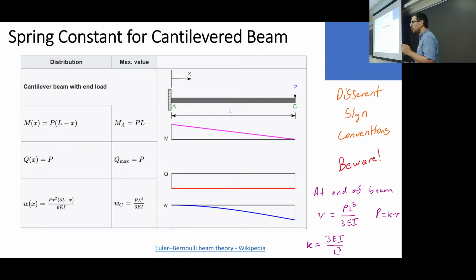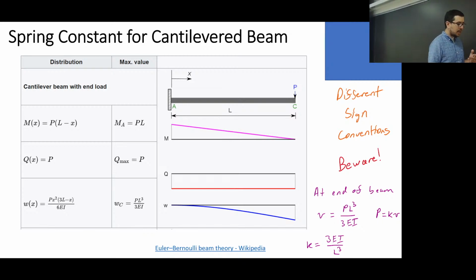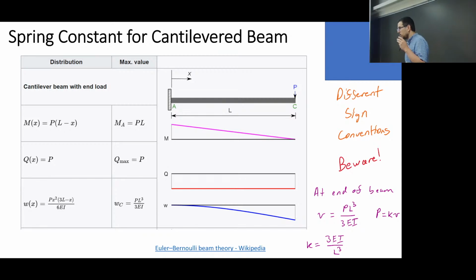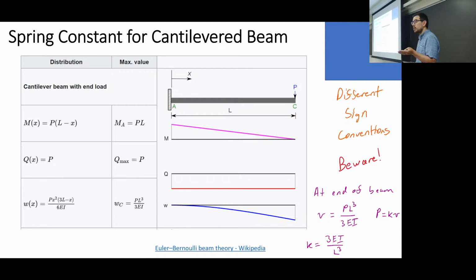Then I would have a K_T analogy, or a K_M if you want. Okay? You could have a torsional spring constant, is what I'm saying. And that's pretty much all I have to say about this. Right? So it's powerful in thinking about the design of mechanical components to be able to come up with a lumped parameter that is a spring constant for your system.